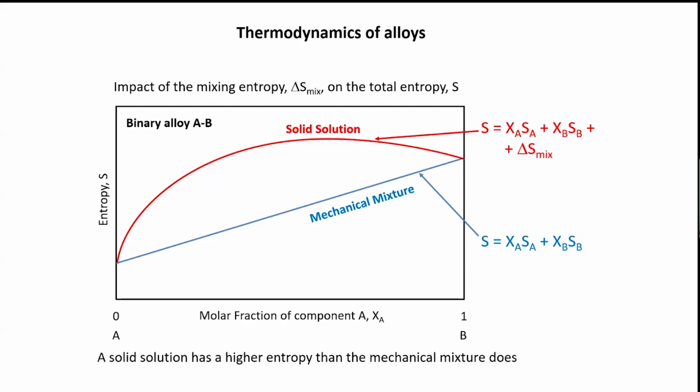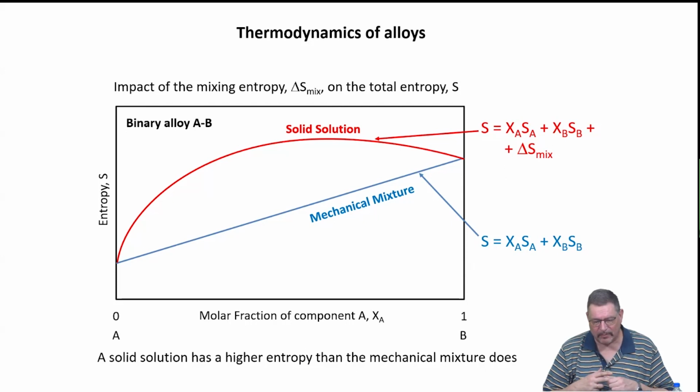Now this is going back to thermodynamics of alloys, and maybe you all know it, how in a binary system we would calculate the entropy for 2 different cases, mechanical mixture and a solid solution. Mechanical mixture is thinking of billiard balls, right? So you have equally sized balls, different color, you mix them, and then it's basically just related to how many of the different colors you have.